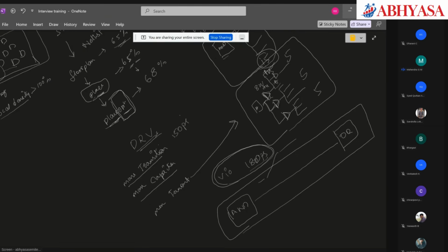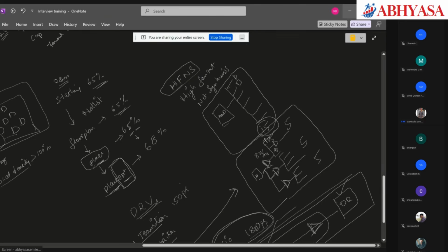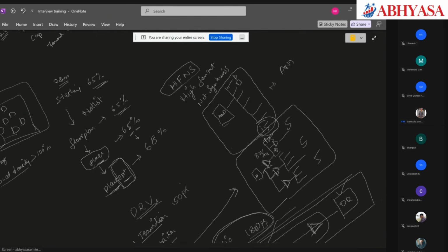Adding buffers in the path. Absolutely. Buffers, right? The single most effective fix is to cut the net and add buffers. So at place stage, for this path, I was just having 2 cells, the AND gate and OR gate. At place opt, I have 4 cells. For the fan out case, at place stage, I had AND plus 15, which is 16.